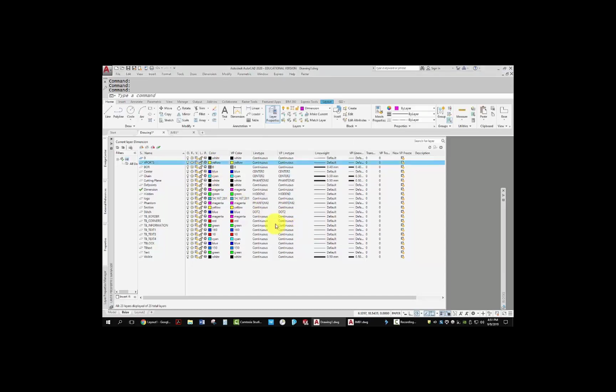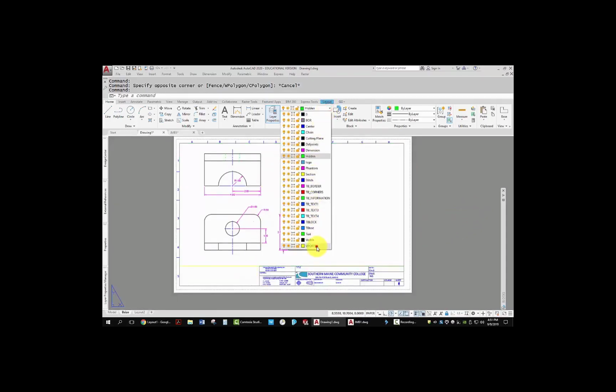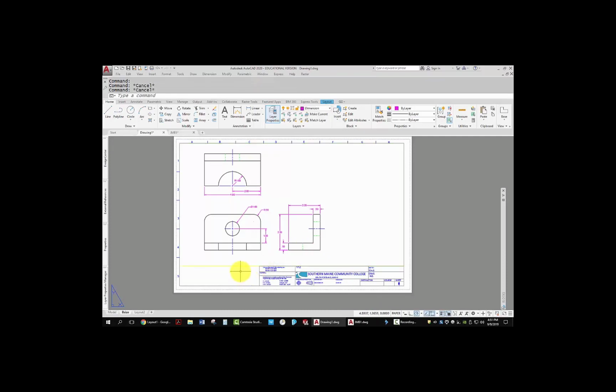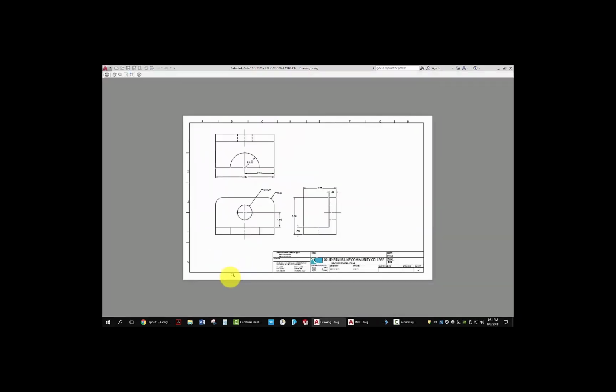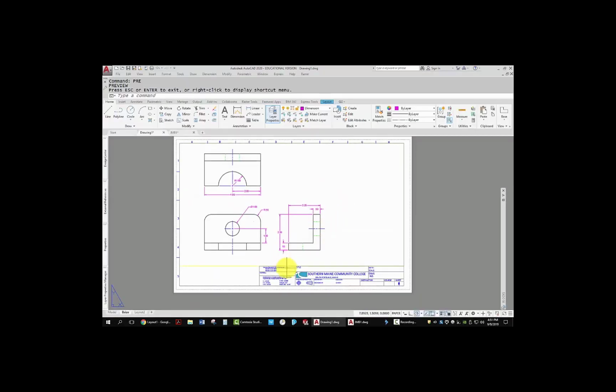And I'm going to make it non-plot, which is that little icon right there. Come back out, take the viewport edge, drop it on the viewports layer. It turns yellow, but if I do a preview right now, the viewport edge itself doesn't show up. Now I need to put some text in here. Material you can leave alone. Over here under interpret geometry.